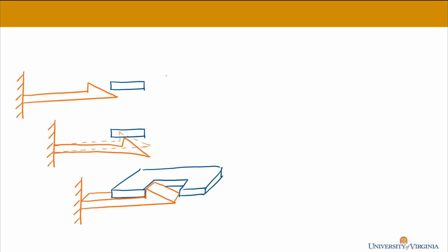Now, imagine trying to remove this part that you snapped in, this orange part. If the idea is that you snap it in and you never take it apart ever, this might work okay. If the idea is you need to be able to snap it in and out pretty regularly, then it looks like it's going to be pretty darn hard to pull that snap back so that it'll be released.